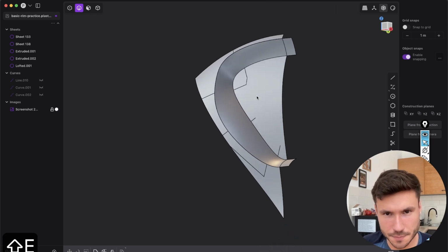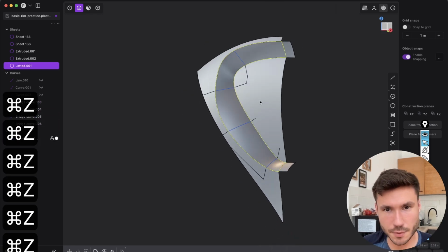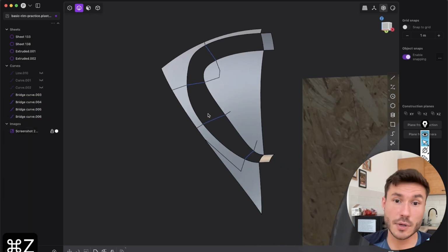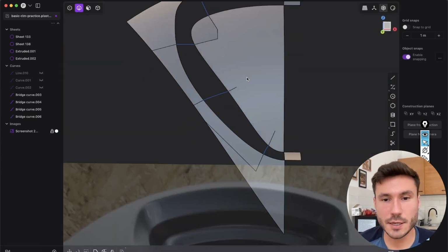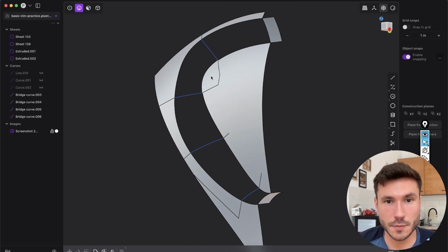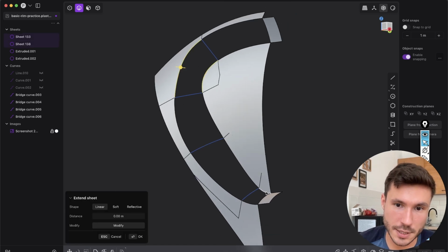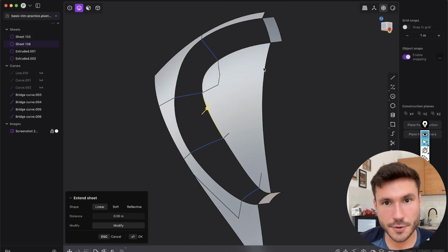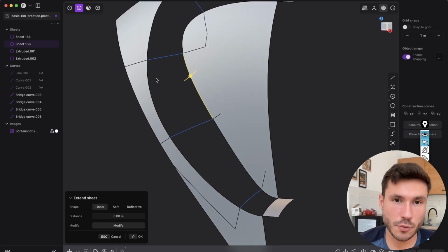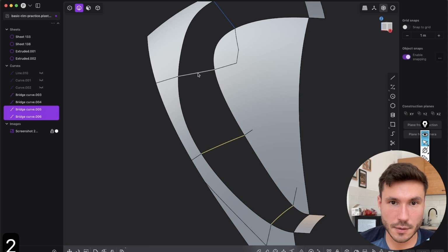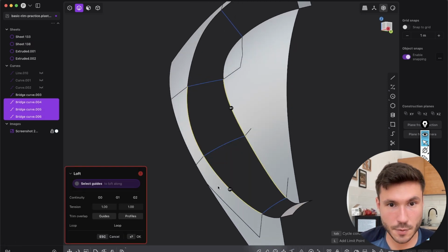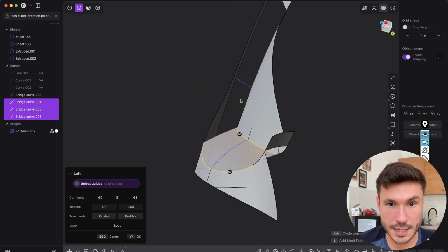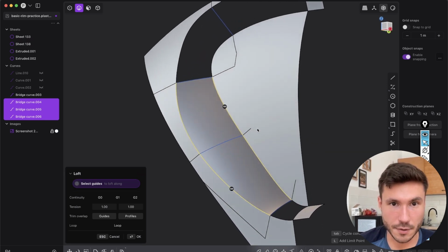But sometimes, if you just go back, because I just want to tell you, sometimes it's better. So you have to see what gives you a better result. So we have those fillets. So these are those sections, right? But we have also very straight sections. So here to the top and here on the side. Sometimes it's better to break it down. So, I mean, if we just first loft those ones here and shift click with G0 and G0, you see, and this surface looks very, very nice.